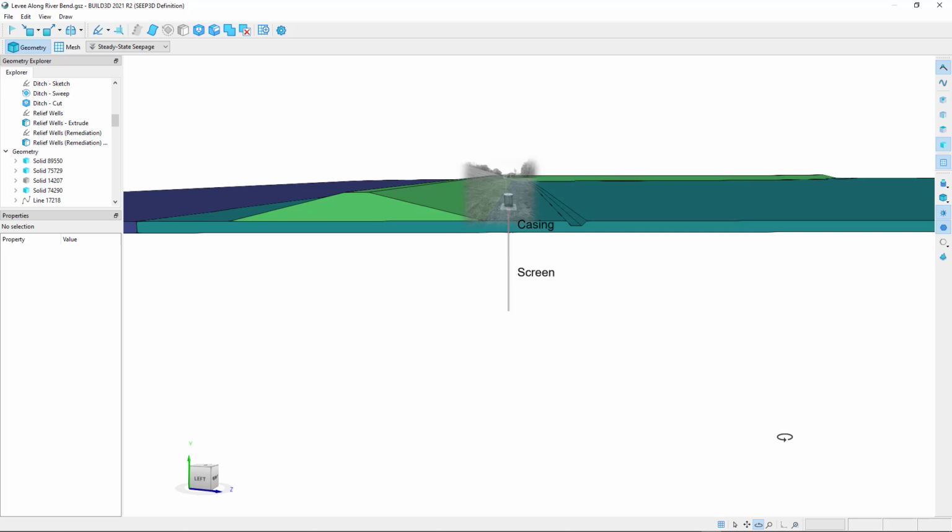Although this may look like a trash can, I assure you it's a pressure relief well. The metal grill simply prevents vandalism and damage to the top of the well. As most of you know, the well consists of a check valve that prevents backflooding and entrance of foreign material. The casing that lies in the blanket layer is impervious, whereas the screen in the aquifer allows water into the well. This system is relatively simple, if not simplistic, and allows water to flow into the screen, up the well, and out of the top of the well.